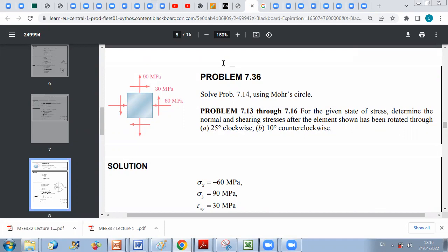If you remember, we have already solved this problem using the formulas developed at the beginning of the course, okay? Before, we just solved using the formulas without taking into consideration the circle. The circle is of extreme help sometimes because you can easily use geometrical techniques to find stresses in any orientation, okay? Of course, you can use both methods. If they don't specify for you in the example, you are free to use the method you want. But if they told you to use Mohr circles, then you should use geometrical techniques.